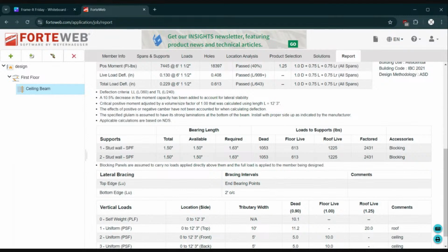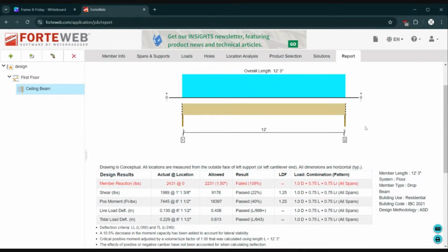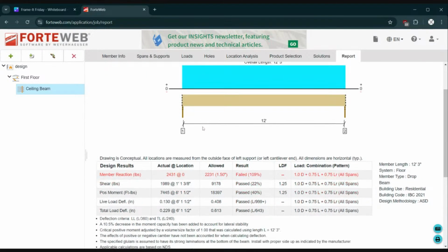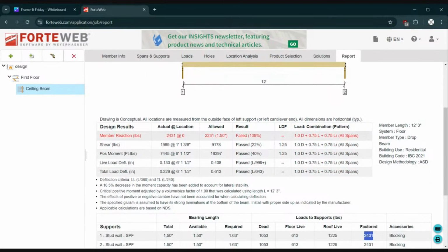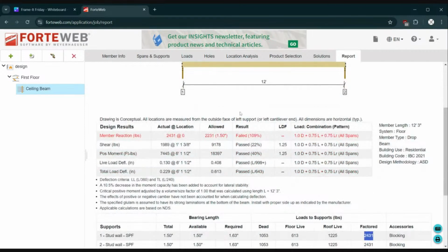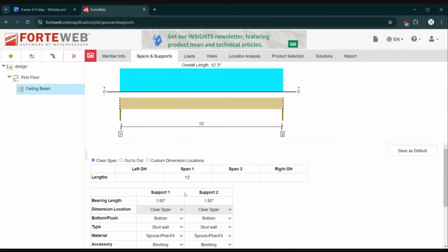So here's where these numbers come from, right? If you put 2,400 pounds on a 1/2 inch by 3.5 inch area, I say 3.5 inches because this beam is 3.5 inches wide. Okay, that's the area for compression that you have. It crushes the wood. There's not enough wood there. It's going to squish. It's going to crush your wall or crush your beam, and that's why the support area matters.